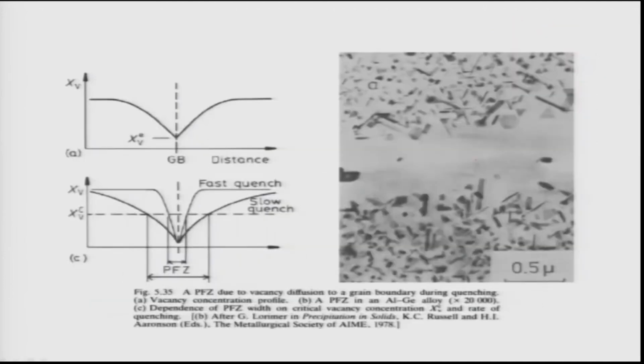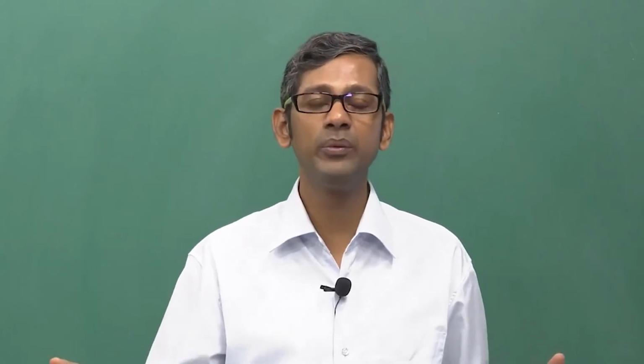Another important thing which I should discuss is the heat treatment cycle which you do. Remember that the first thing we do in the heat treatment cycle is solutionizing at a high temperature, about 500 to 550 degrees Celsius for the aluminum copper alloys. Because of the solutionizing temperature, all these theta prime precipitates get dissolved into the alpha matrix, and at a high temperature obviously this is done. Therefore a large number of vacancies will be created at high temperature. As you know, the equilibrium number of vacancies depends on the temperature in a particular material. So at high temperature a large number of vacancies are created, and they remain as equilibrium defects.